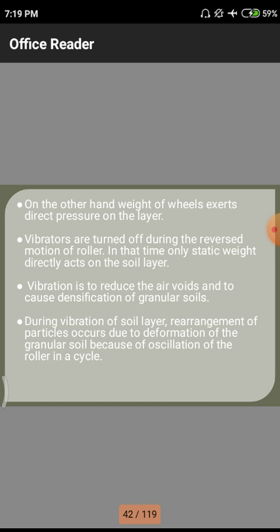While we are telling, there may be a chance of skipping a few words in a short span of time, so whenever we are observing or showing these, we don't have a clear-cut idea. Whenever you go into the fields and observe these rollers, you should have a clear-cut idea of how the driver is moving, what reaction time they take for a particular soil strata, in how many layers they are dumping the material, and for each layer how many vibrations they are giving. That means the number of vibrations in a particular length. All those you have to observe.